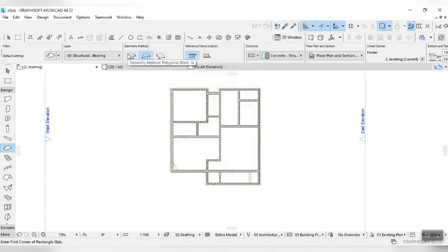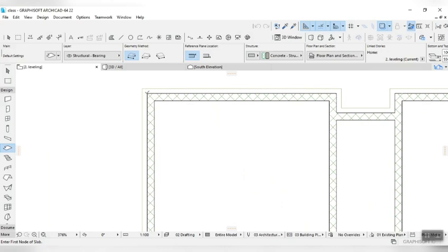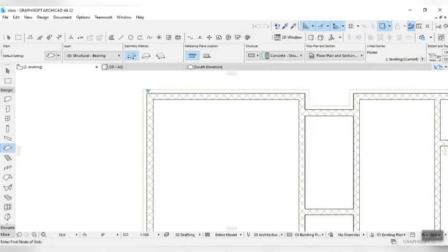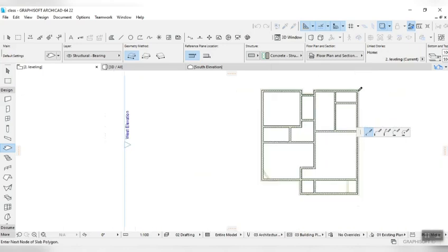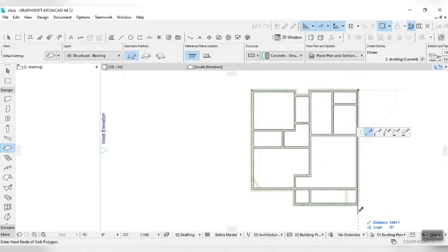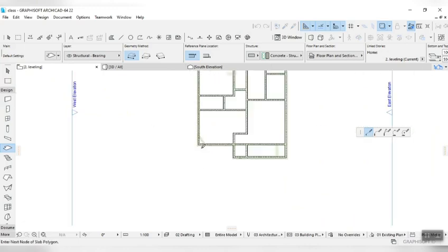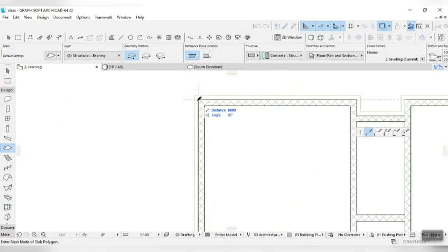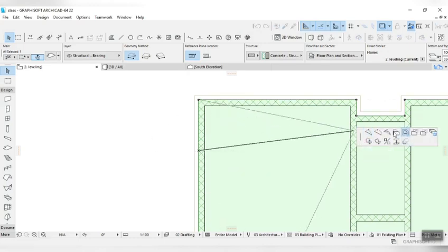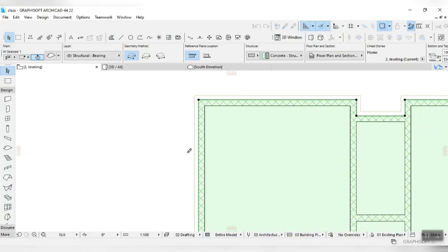You change to this polygonal method. Then we pick all edges. You just have to pick all edges because you're working a slab here. You pick all the edges, all the spots. This is what you need to do. You pick all edges. You could zoom so you see very well. All edges will come down to the spot. You let go. Okay, so what you just need to do is come down to here, offset all edges to 300 millimeter. Click OK.